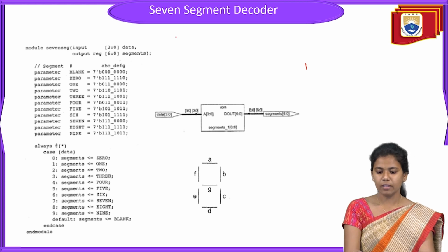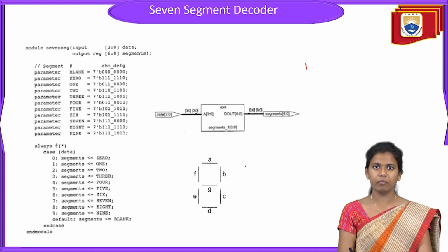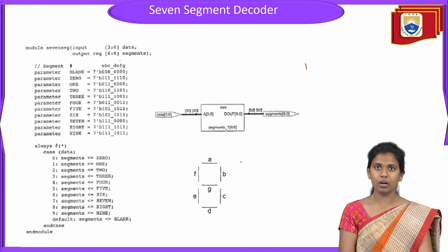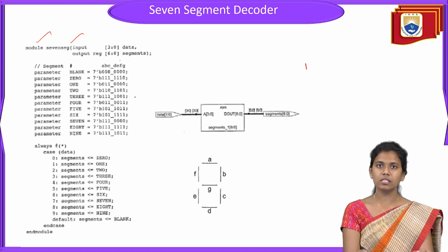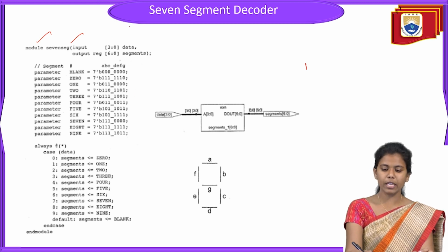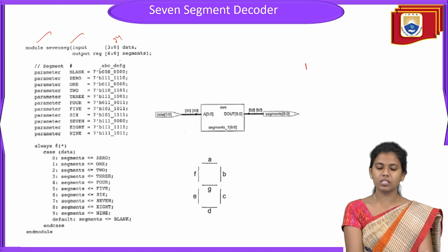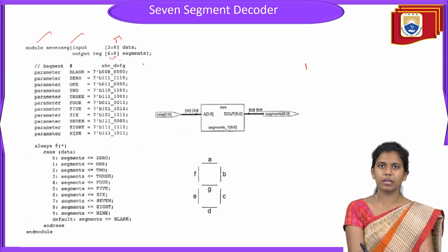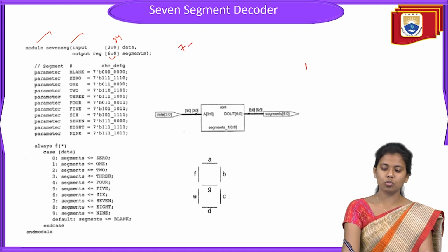Okay, so here this is nothing but a 7-segment decoder. In the 7-segment decoder, we will see how the program can be written and how the output can be obtained. Here my module is a 7-segment display, and the input data is data[3:0], that is 4 bits of data, and the output register is seg[6:0]. Why? Because it is 7 segment, right? So 7-segment data means totally 6:0.